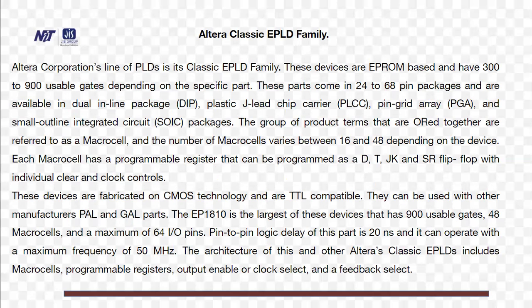The EP1810 is the largest of these devices that has 900 usable gates, 48 macro cells, and a maximum of 64 I/O pins. Pin-to-pin logic delay of this part is 20 nanoseconds, and it can operate with a maximum frequency of 50 megahertz. The architecture of this and other Altera Classic EPLDs include macro cells, programmable register, output enable or clock select, and a feedback select.